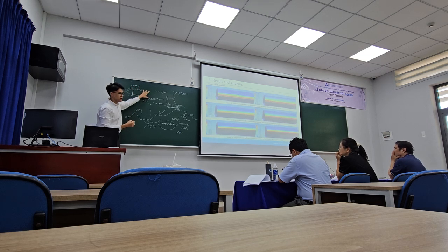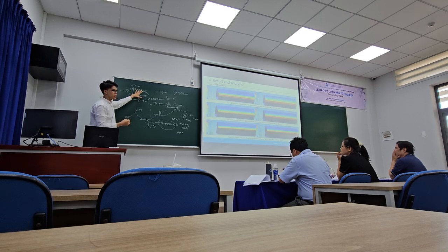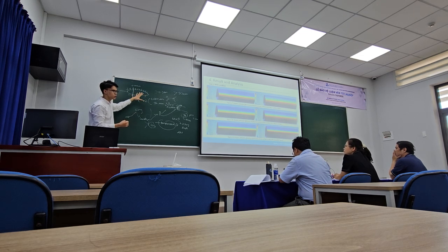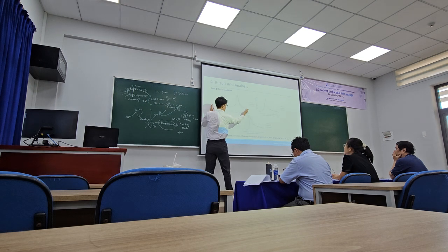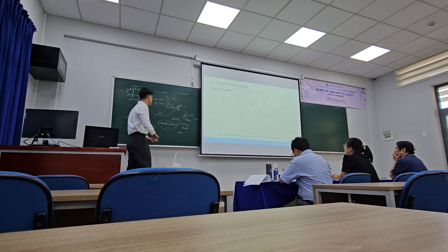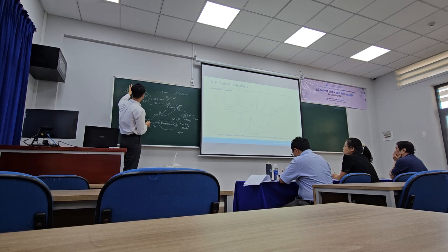Because if we survey all of this, we don't have any way to ensure that I'm correct. Following the article, we just survey from here to here, and this is also the place the supercooled large droplets will hit. We survey less here because if the supercooled large droplets attack on this, the normal vector will be in contrast, meaning they move away from the airfoil, so we do not have anything. And as you can see on the screen, if we expand it with 0 over here, we focus on the highlight point to 200.